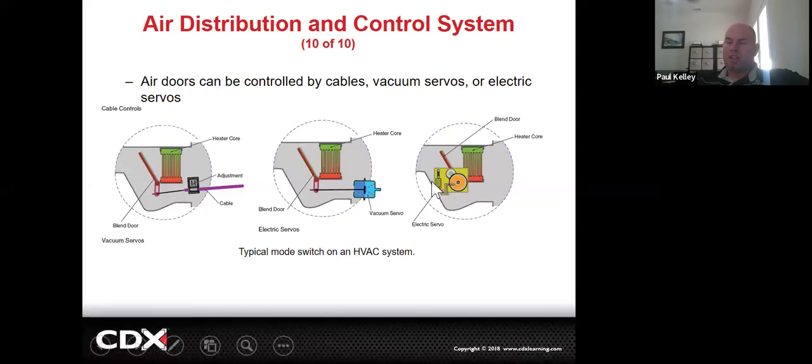So these can fail in different ways. The motor can go bad, in which case it won't move. But the sensor can go bad, in which case it has the power to move, but the sensor doesn't know its position. It would likely set a code. Right? So they're both. It's an input and an output in one. And you can't change the motor separate from the sensor. And you can't change the sensor separate from the motor. You just get the whole actuator.